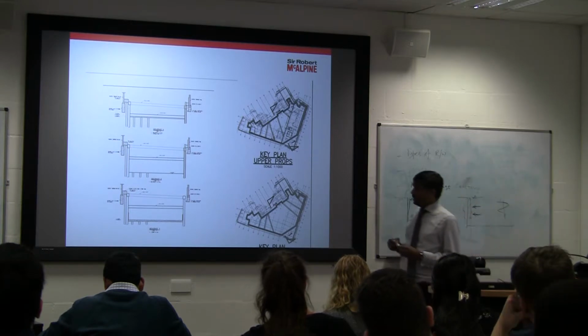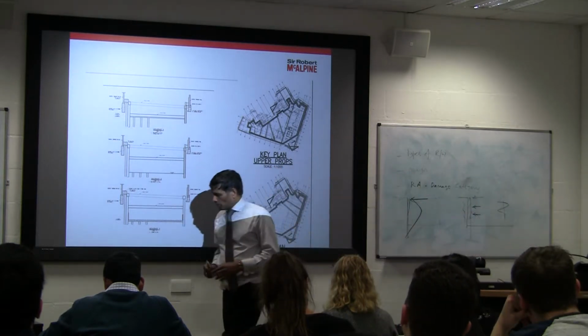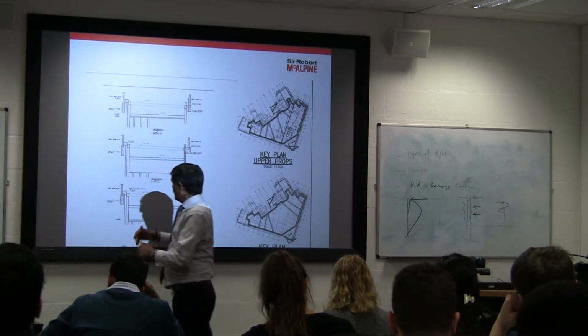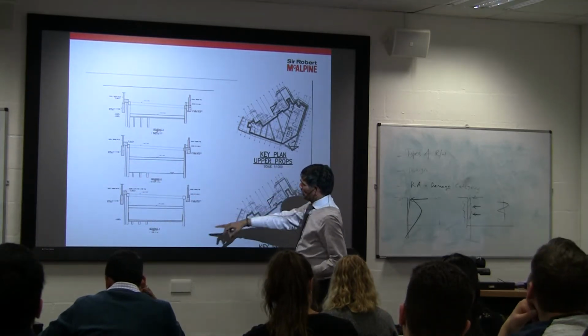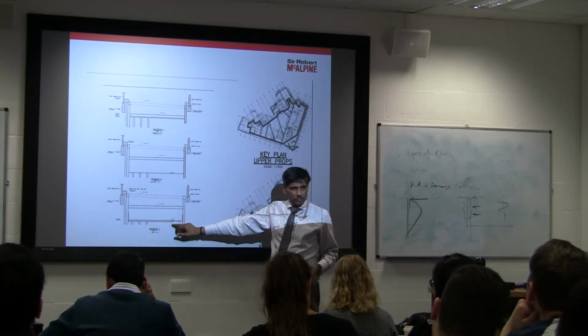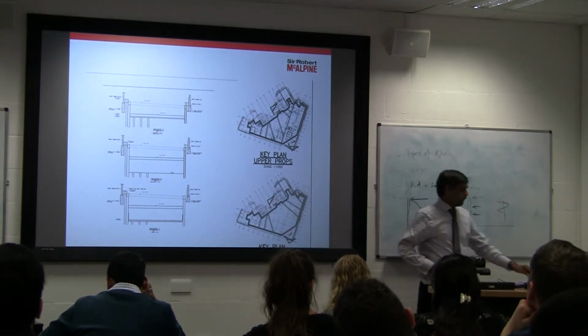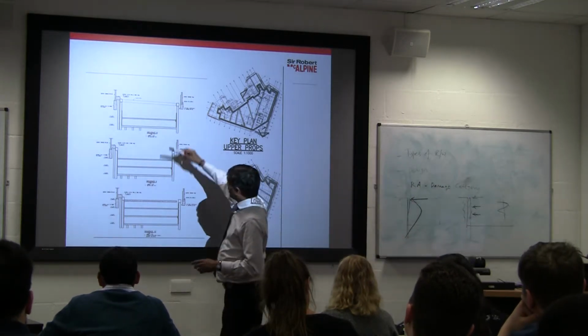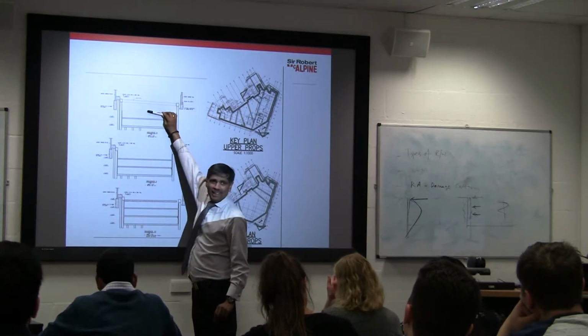So you have to decide whether we should put 2 levels of props or 3 levels of props, and then proceed sequentially to the next level, to the formation level. And then, as I was saying, now you've gone down to the bottom, so you've got to think how you are building it up.